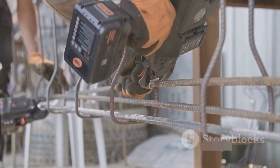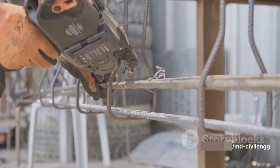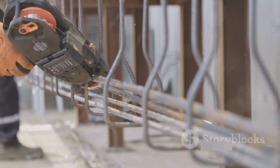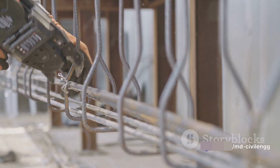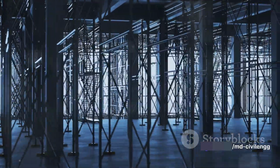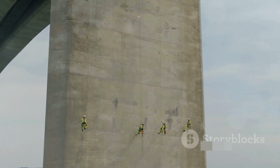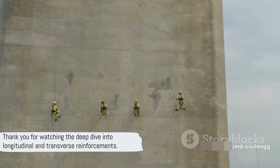But what about helical reinforcement? The diameters of helical reinforcement are selected based on a specific formula involving the gross area and the core diameter. The pitch of helical reinforcement should not exceed 75 millimeters, and it should be at least 3 times the diameter of the steel bar forming the helix, or a minimum of 25 millimeters. As you can see, both longitudinal and transverse reinforcements have specific requirements that must be met to ensure the stability and safety of the column, and by extension the entire structure. That's all about longitudinal and transverse reinforcements.